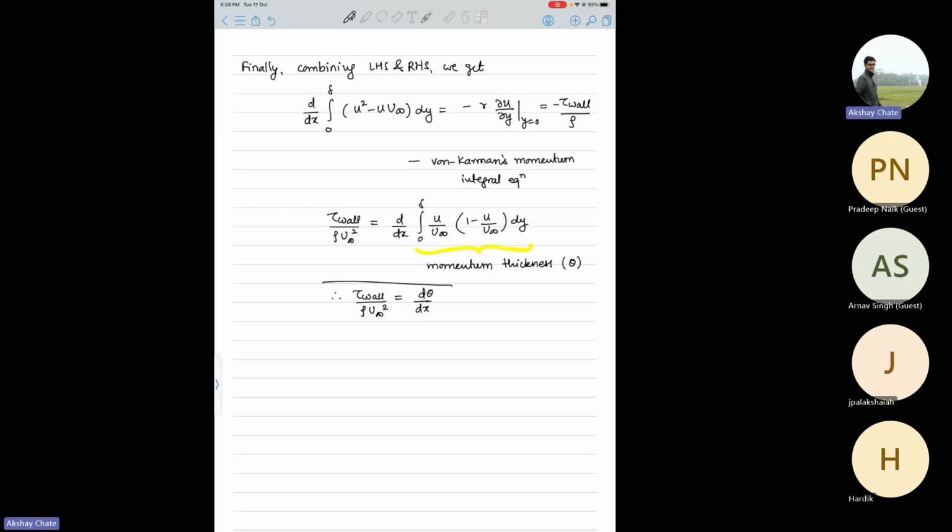So this is your final equation, basically, not the solution. And keep in mind, this is valid only for a flat plate. If it is not a flat plate, we will have one additional term, and that will come because of the pressure gradient. Anyway, that is out of the scope for this course, but you should remember, it is valid for a flat surface.